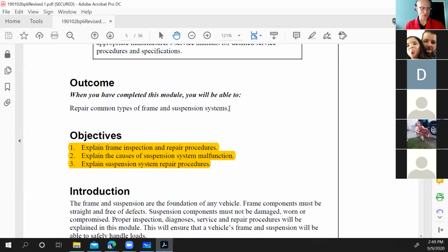You actually should never, ever touch the flange with any kind of drill or cutting torch or welder, anything like that. Very rarely, and only under special circumstances will you actually perform anything like that to the flange. As soon as you start putting holes in that, it makes it so weak immediately, and it'll make a point where it can bend and not come back.